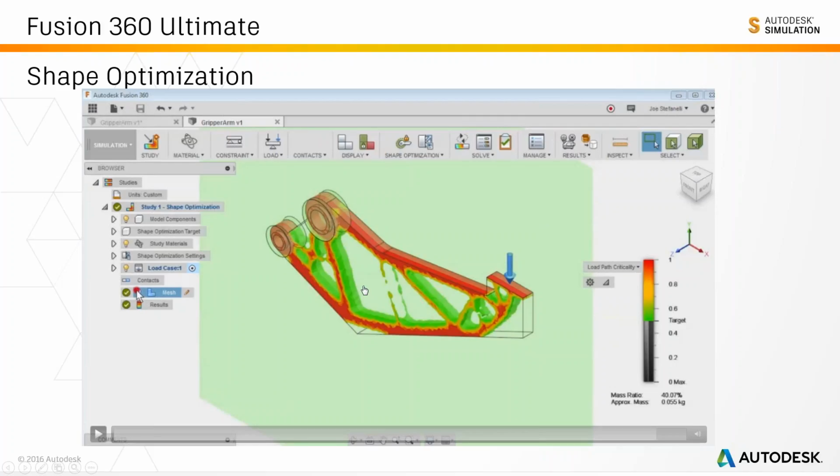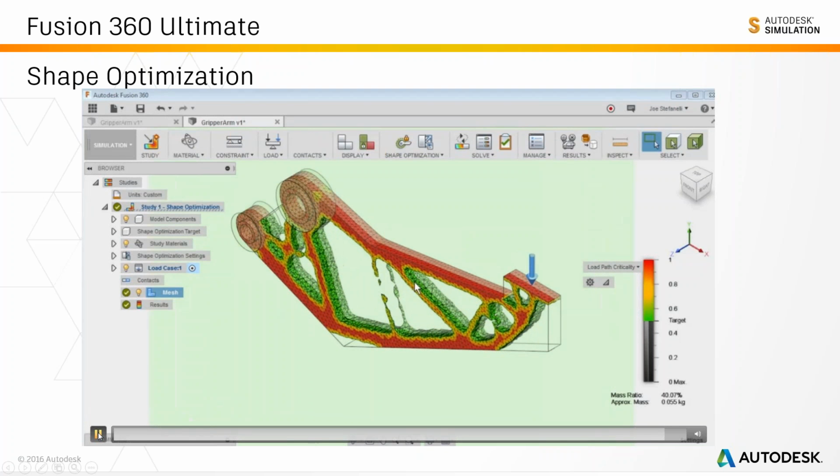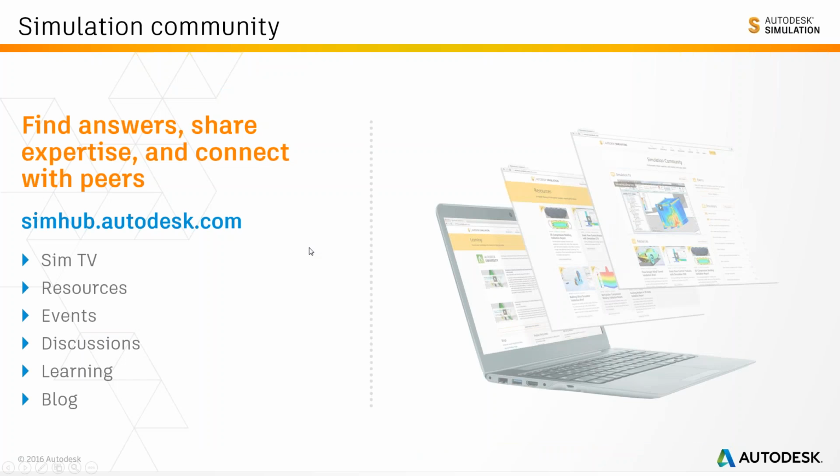So areas in this volume, or areas in the center where say the material is not loaded, all those elements in those areas are going to be removed, and areas which are critical for the proper functioning of this in terms of enhancing the strength, maximizing the stiffness, are going to be preserved and painted in red here. So this is the final result here.